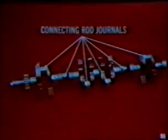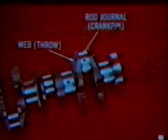The main bearing journals are all in a straight line, and they alternate with the offset journals, which are for the connecting rods. Notice that the rod journals are at various positions around the shaft, so that the pistons will be at different places in the cycle. Another common name for the connecting rod journal is crank pin. The side supports for the rod journals are called webs or throws.